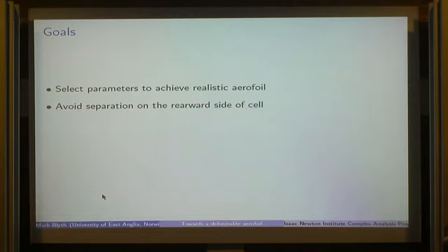So let's be a bit more clear now about what we mean by an aerofoil, or realistic aerofoil. I want to tune the parameters to achieve that. It doesn't look all that promising so far. And I want to do that so that I get the characteristics of a regular aerofoil. I want to minimize separation. So if there is separation of the boundary layer on the top, I want to push that to the trailing edge as much as possible. I want to have as little drag as possible and as much lift as possible.